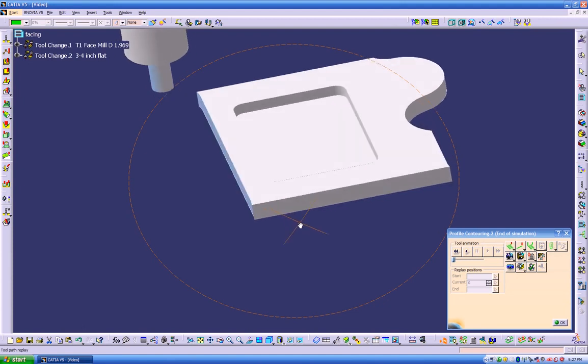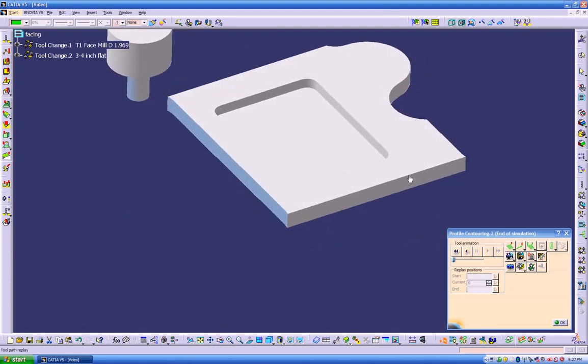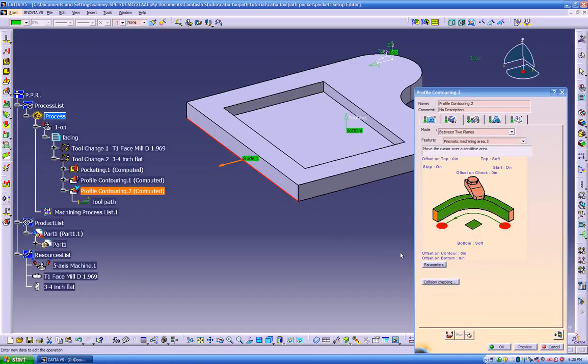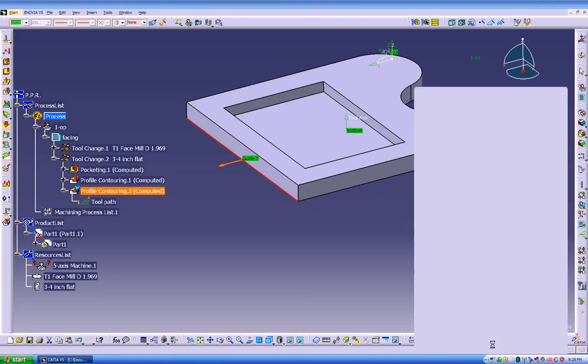Beautiful. So now we're gonna take the clamps from those two side walls and put the clamps over here. We have to specify that in our setup sheet for the guys in the CNC shop. And then we're gonna make another operation to remove this and this. So I'm gonna save this. We're gonna click OK over here.